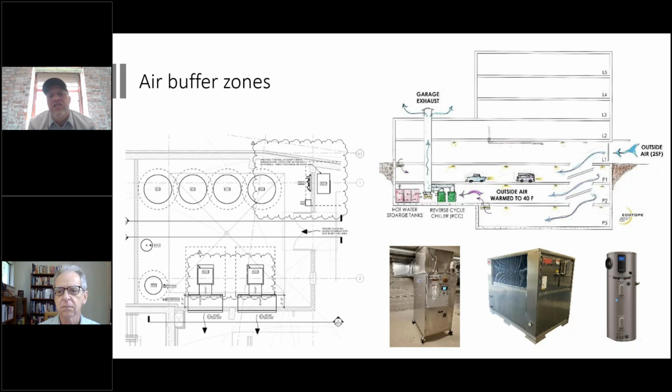Where you discharge your air when you're in a garage is important. You do have to pay attention to it. If you're buried in the corner, deep in the bottom, I would recommend trying to push the air up a level or two, especially with below grade basements, which come with big buildings usually. But you really want to try to get that air out. The discharge air is 15 degrees cooler. You don't want that to be in a small confined space.